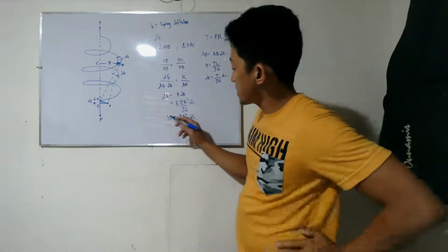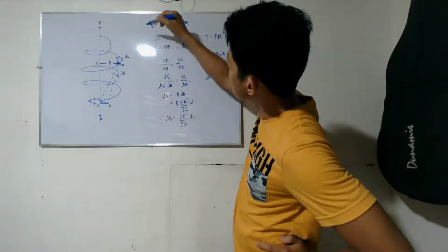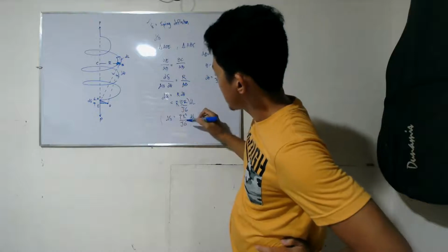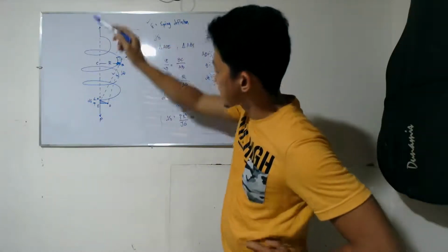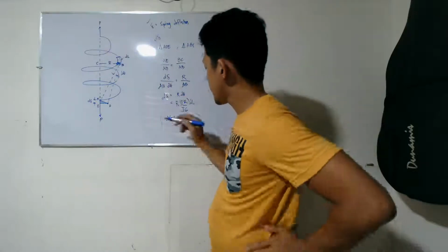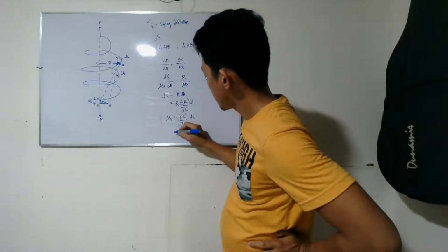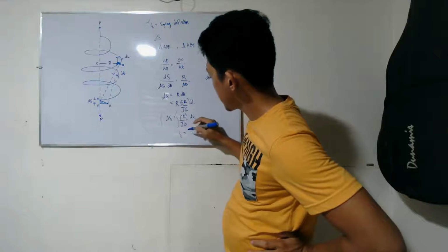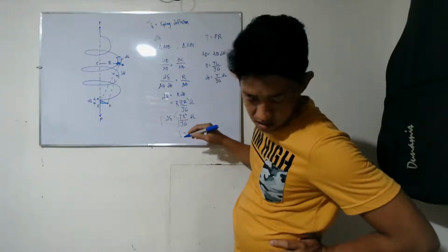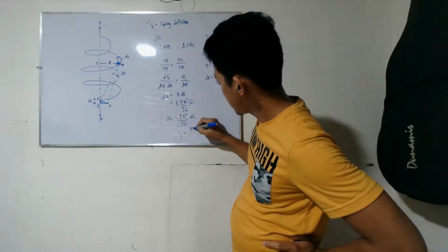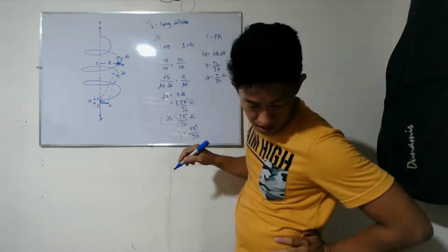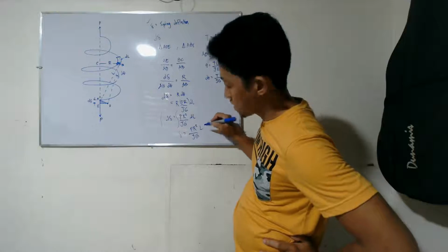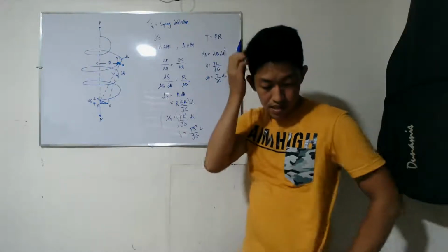And then, we will integrate this one. That was just for a small length. Now we integrate over the whole length. We'll get that δ is PR squared, constant, over GJ, times L. Okay?